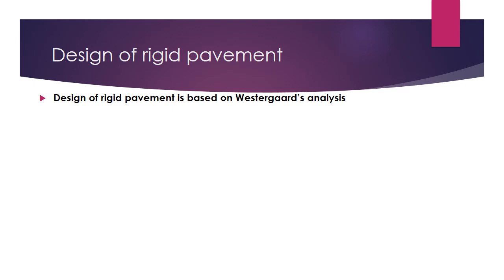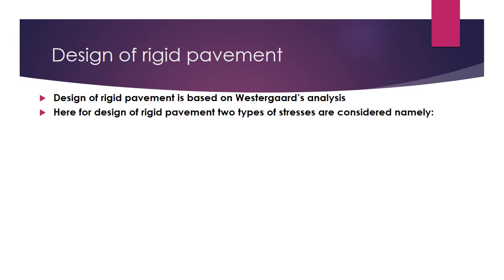Westergaard's analysis. Now, Westergaard is considered a pioneer in providing the rational approach to analysis of stresses in rigid pavements. Here, for design of rigid pavement, two types of stresses are considered, namely wheel load stresses and temperature stresses.